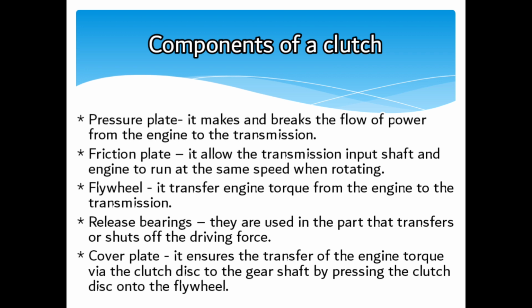We have another component called the flywheel. The flywheel does many things. It acts as a balancer for the engine. It dampens engine vibration caused by the firing of each cylinder. It provides a smooth machined friction surface that the clutch can contact. But its main function is to transfer engine torque from the engine to the transmission. That is the main function of the flywheel.